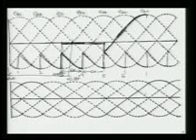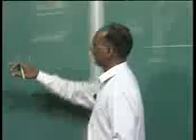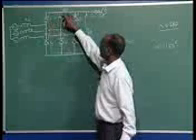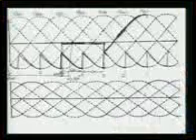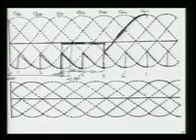Now 1 is fired. Then A is coming on the cathode of valve 3 and B is also there. So the voltage across 3 is EBA, because B is here and A is coming here. So this is EB minus EA voltage, always we are drawing the direction. So EBA, and now you have to see where the EBA is. You can see EBA is this one, and it will follow here and then it will continue.